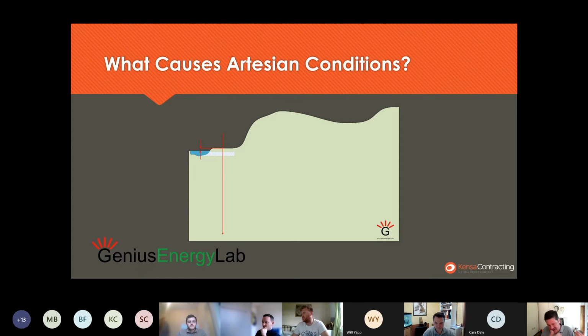So surface water, even in hydraulic contact with the surface of a borehole, tends not to be too much of a problem for us. However, a much greater problem is if we have something like this. So, for example, up in the hills here, we've maybe got some porous rock, and that rock is going to get rained on, and that rain is going to filter over thousands of years down through the rock. And what can happen, the water level perhaps is up there, right up in the hills. And so when we hit that water-bearing strata beneath, then what we're going to get is an equalization of pressure, which is going to force the water up out of the ground. And this is when you get these very big water spouts happening. So that's the general cause and the main concern for Artesian conditions.